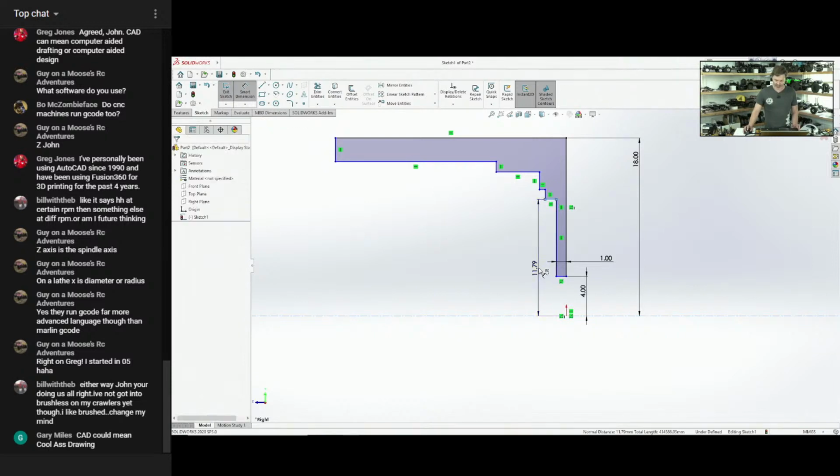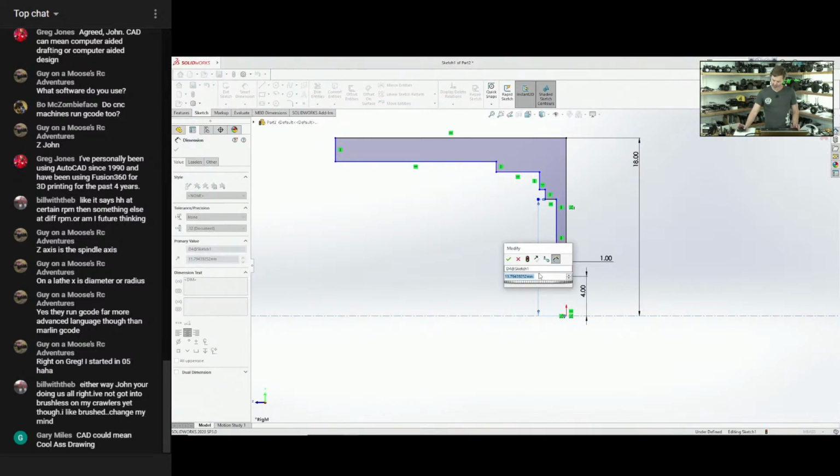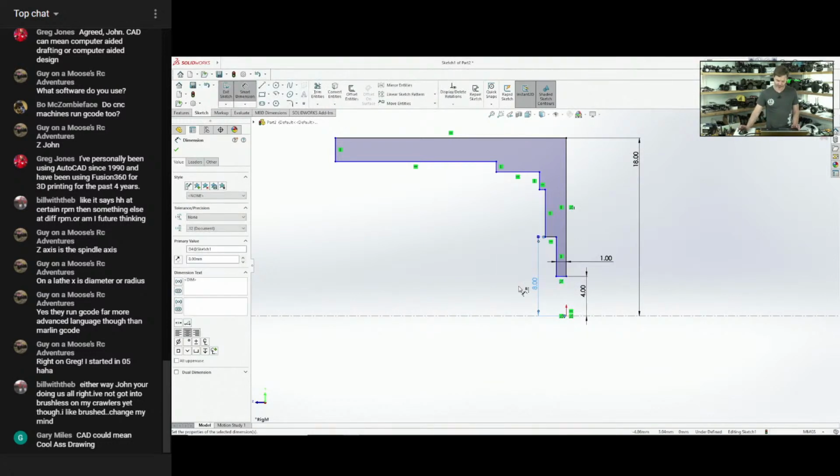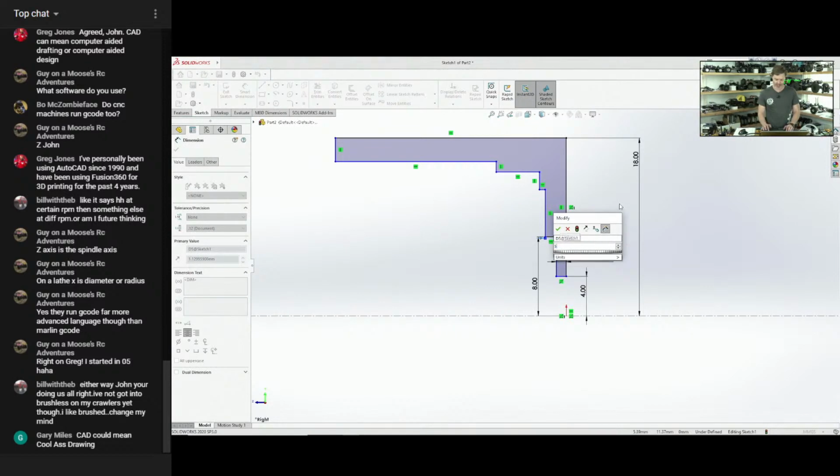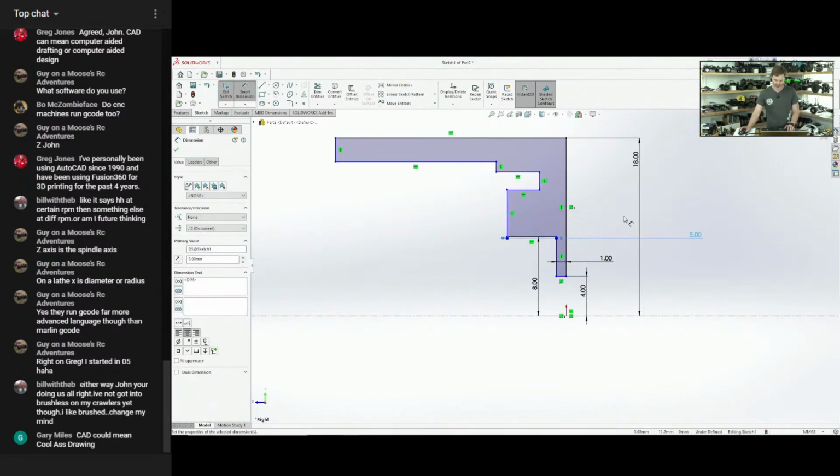We'll do bearing pocket. The bearings are 16 millimeter bearings that I use in mine. So we're going to have an 8 millimeter radius, 16 divided by 2. One thing that I would like to make note of is that so many companies list their ball bearings as being oversized in their motors. And so far, I've not seen a single company that uses 16 millimeter bearings. They all tend to use either 14s or 15s.